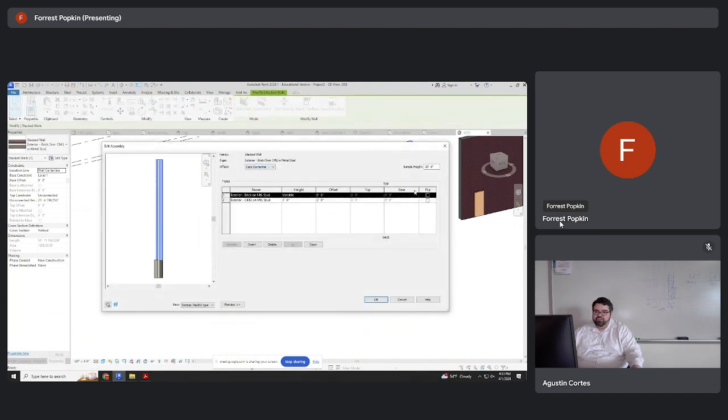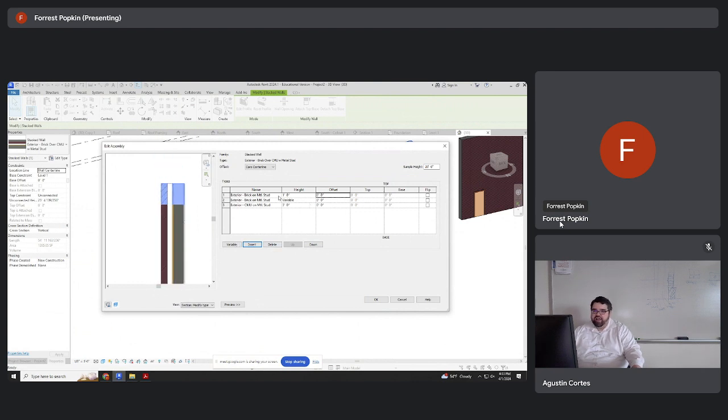Okay, so the versatility of this is pretty much boundless. If I understand that I can add yet another wall type, I might be able on the top to have sort of a ribbon that's a different color or a coping or something like that. So you'll see here, if I zoom in, it's creating a different value there. So if I go to a different wall type here, I could say, oh, for the top of my building, I might want it to be generic masonry. And then you're going to have to figure out if you want that to be offset. So if I want that to be offset, watch what happens to the section. It moves it out or moves it in. It moves wherever you want it.